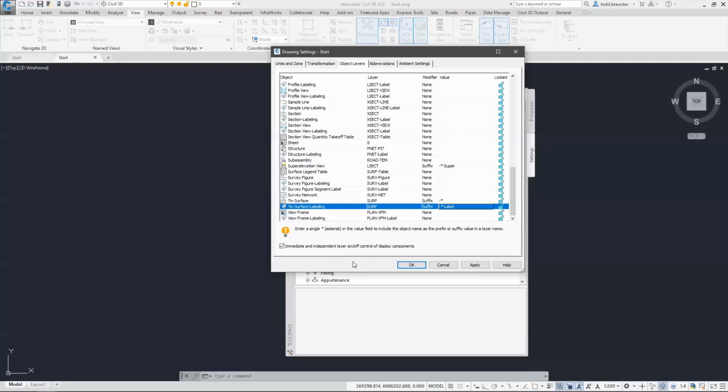If you untick this, then irrespective of what layer and subcomponent is actually set on, it will turn off when the primary source layer of the object is turned on and off. It's kind of like the block behavior when you're using freeze and thaw. But this time it's different because you can control it at an object level. So for my exercise today, I'm going to turn it off, and I'll show you what happens a little later on when we're making some alignment styles, and you'll see what this impacts.